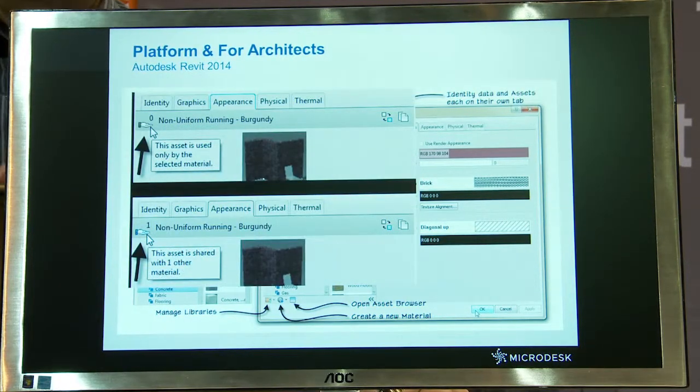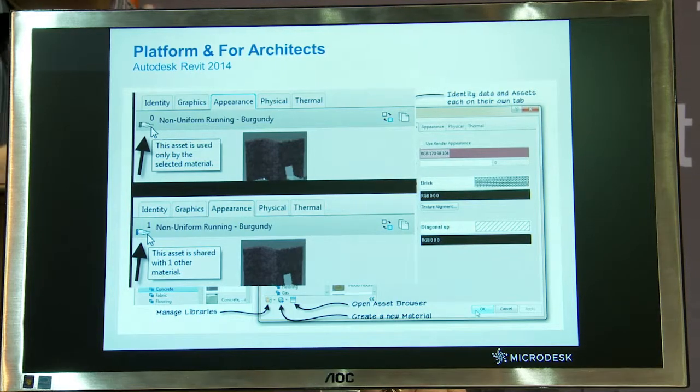Oh, and out of those things that you can access, which is really cool, and this happens all the time in firms that do not have standards and an established workflow for things like materials. You know how many times I've seen people assigning a material like concrete to a wall, but then they delete that material and forget that they applied it to something else, like the floor. Now they removed it from the floor, but because it was already assigned, it removes it from the wall as well.